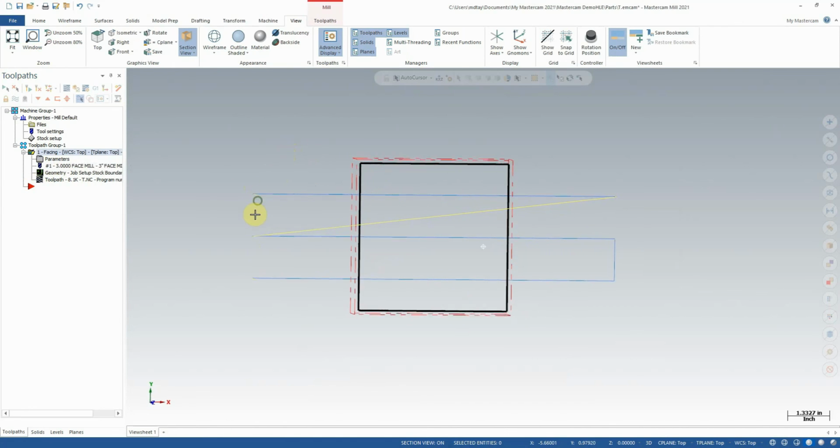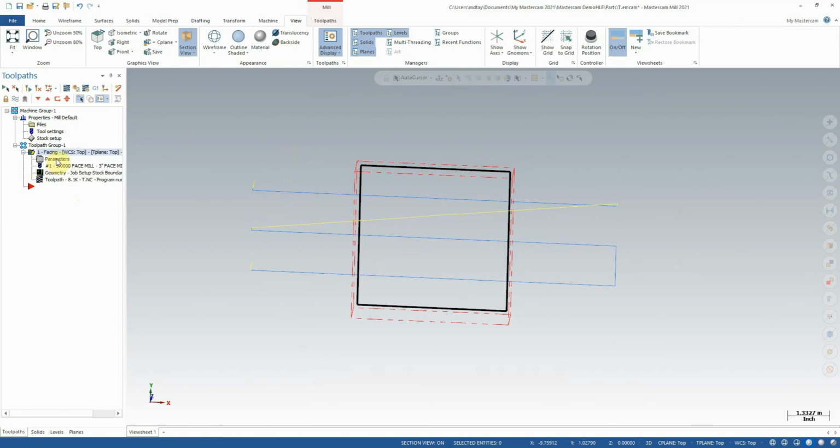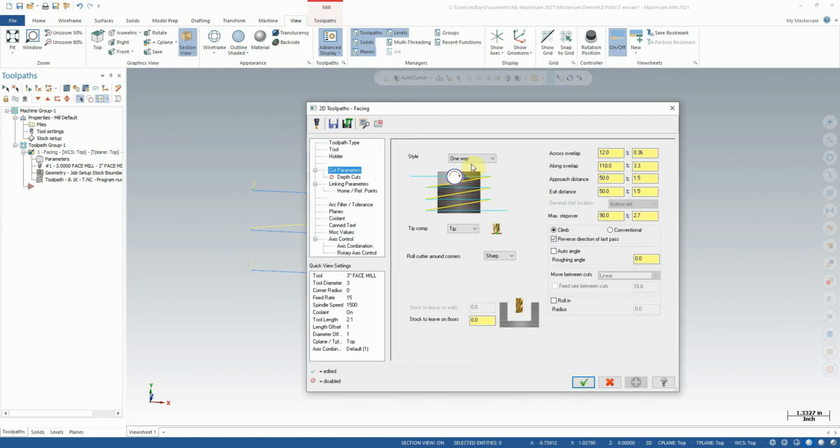So let's see now what else is happening. So our tweaking of that setting does make sense. I do believe that was the correct thing to do, but there must be another setting interfering. Okay, so I suspect what's happening is that this across overlap is based on each side. That's probably what's happened. So by saying 12%, that was setting the overlap to 360 thou, which while that is within our tolerance for one side, it won't be for 2 sides.